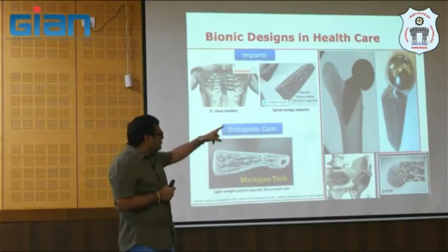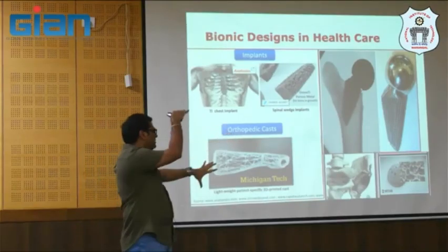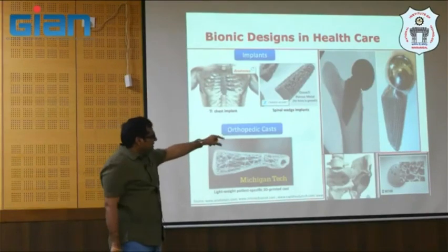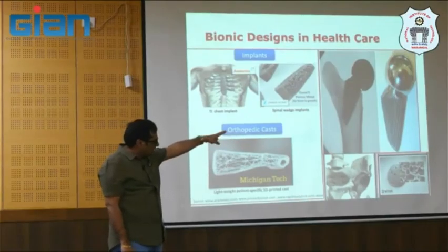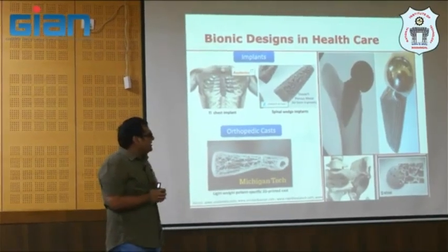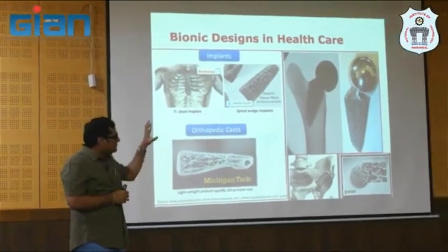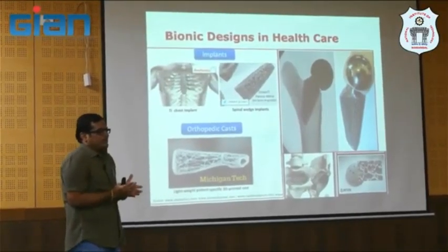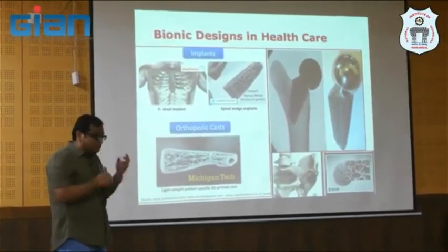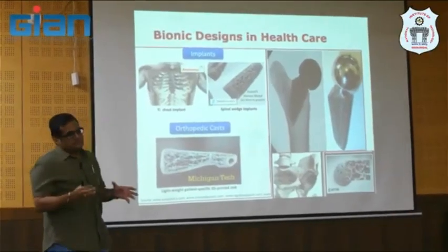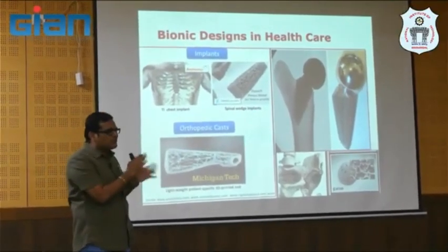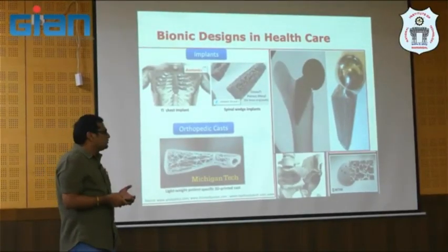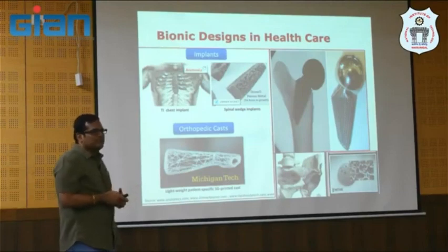the kind of femoral ball here, all the weight will come there, and that's why you have a solid region over there, and you have a cell growth region here. So the porous part there, right? None other than additive technology can produce this in a single setup. Somewhere it is solid, somewhere it is porous, and that too you can control that porosity, right? Porosity may be a defect from our usual aspect, but here you are intentionally creating a porous structure which mimics the anatomy of the patient or the user, right? So that's where we need to personalize those kinds of designs.